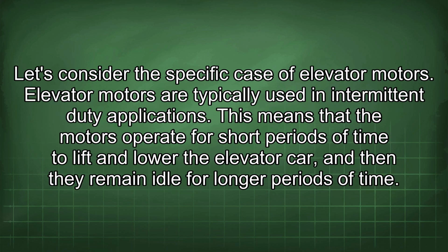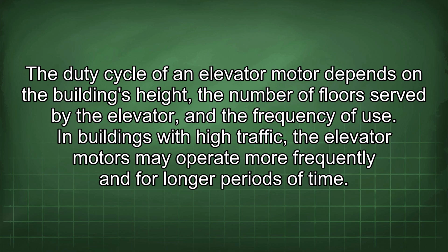Let's consider the specific case of elevator motors. Elevator motors are typically used in intermittent duty applications. This means that the motors operate for short periods of time to lift and load the elevator car, and then they remain idle for longer periods of time. The duty cycle of an elevator motor depends on the building's height, the number of floors served by the elevator, and the frequency of use.